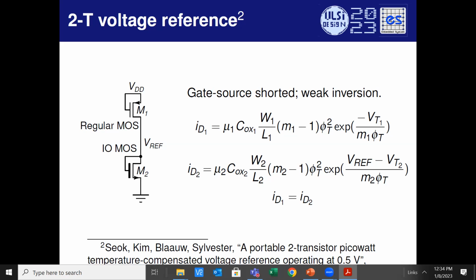If I put two MOSFETs, then I'll have double the leakage. So that tells you that if I double the width, then the leakage will double. So now we're saying that the slope is directly a function of the ratio of the sizes of the devices. So log of that. We can control it however we want.